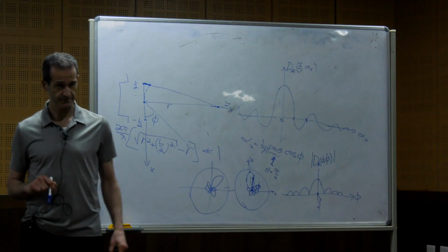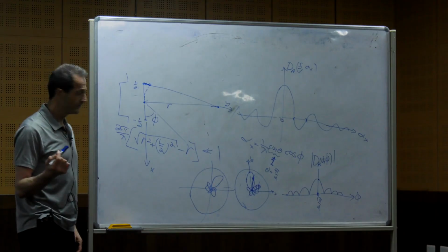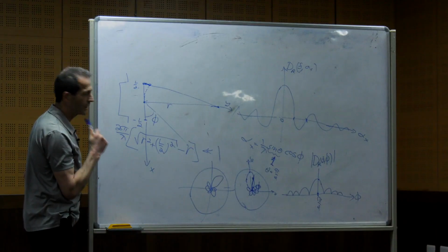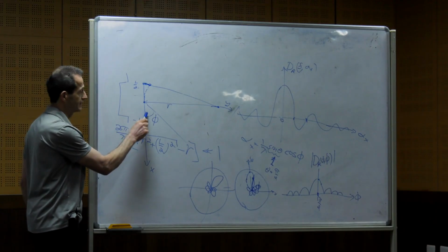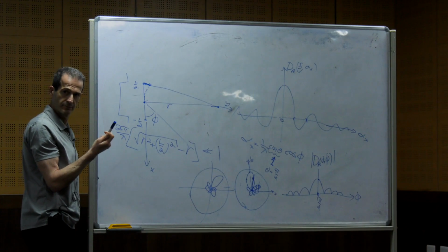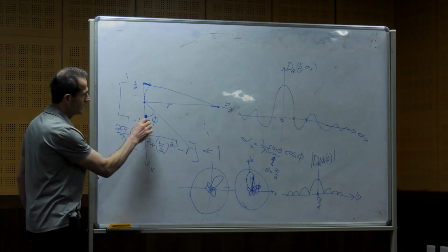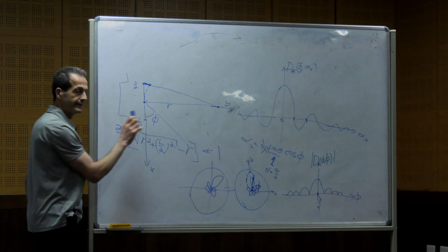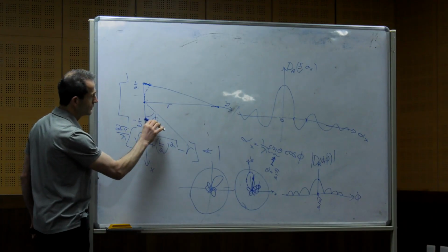How do I do that? Okay. So one possibility is to change the aperture function. What does it mean to change the aperture function? I will add in the aperture function phase response. So it will not be like that. It will be complex, of course. It's a complex number for each frequency. And for each point along the aperture, I will put here the correct phase such that the signal that comes from this will be accumulated.